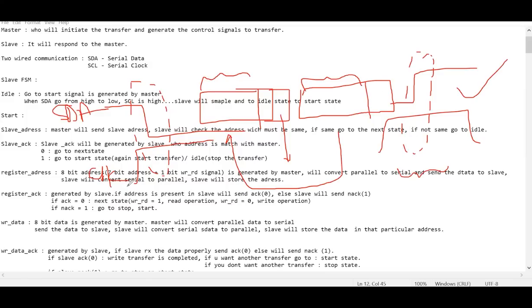Okay, the same thing you can follow for UART also. In UART also we have start condition, address, data, parity bit, stop condition, and like that you can write the states. But in UART we have written it in a transmitter block, receiver block, baud generator, like that, right? So this is a different one. Like that, tomorrow if you see APB, it has a different format, like it has some finite state machine, and it has the waveforms. Okay, so this is the I2C protocol.